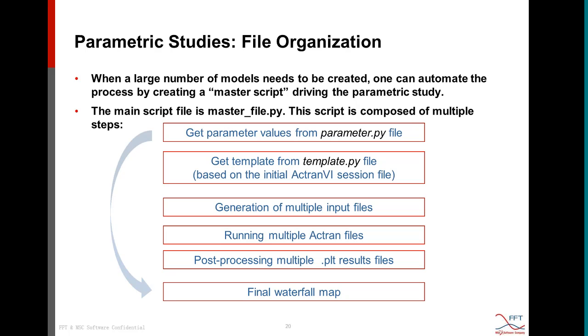This master script will read several other files, including the template files, which are initially dumped Actran VI sessions, but also the waterfall viewer sessions. The master script will also read the parameter file, which defines the parameter values to be studied. And then, of course, we will need a mesh file that supports the physical domain.